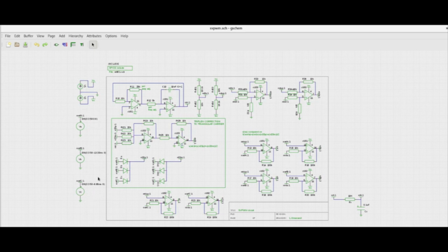Now one can add the triplen third harmonic to the input reference wave shapes themselves and then use it for modulating, or you can add the correction to the carrier itself and then not add any corrections to the input reference wave shapes. It is easier to add correction at a single point, that is, instead of adding correction to all three phases, you can add the correction to just the carrier and then get the same effect.